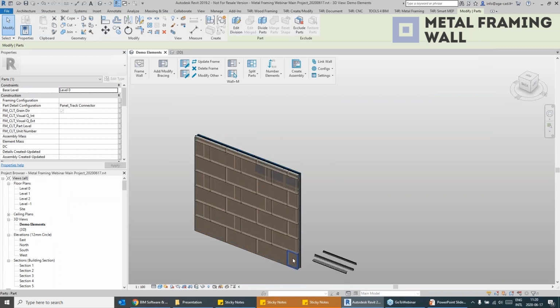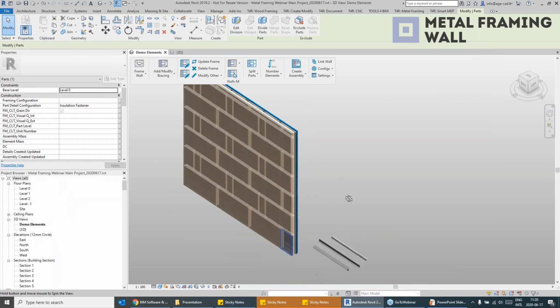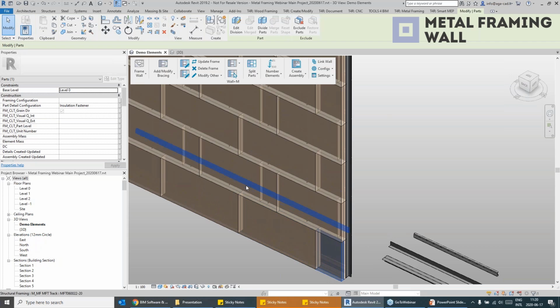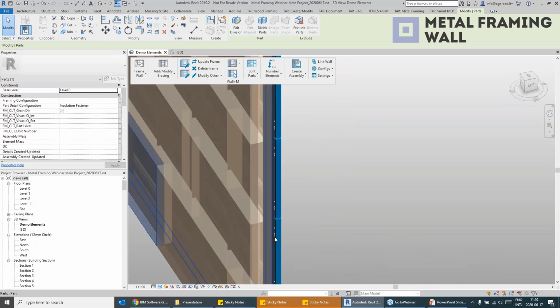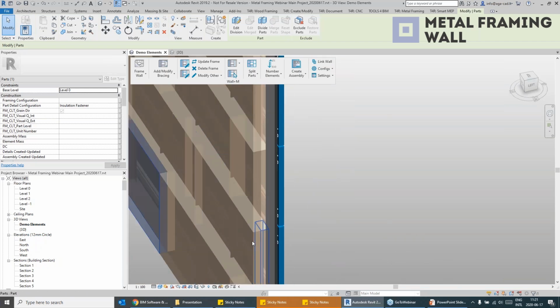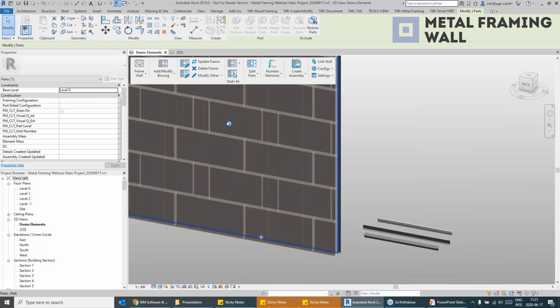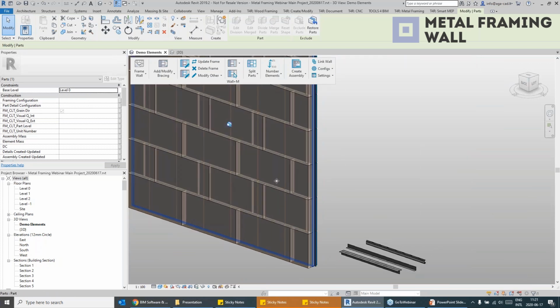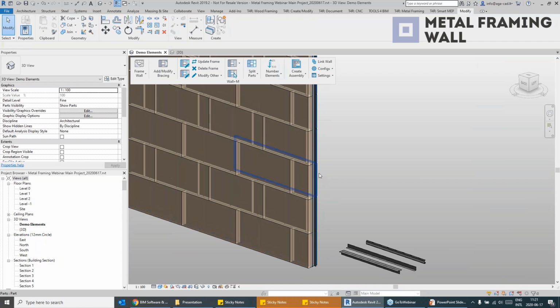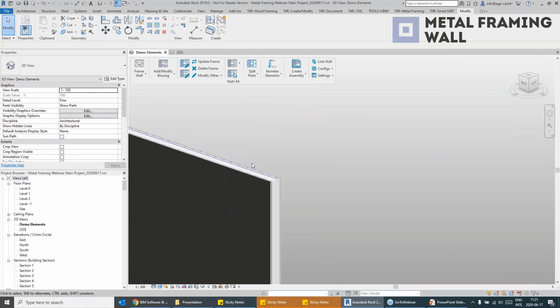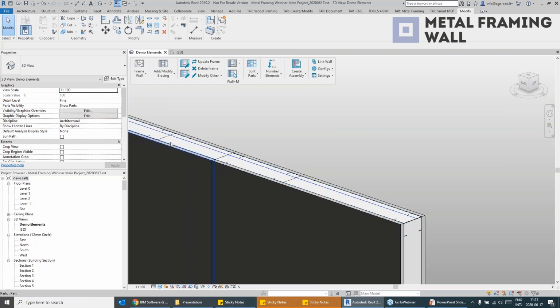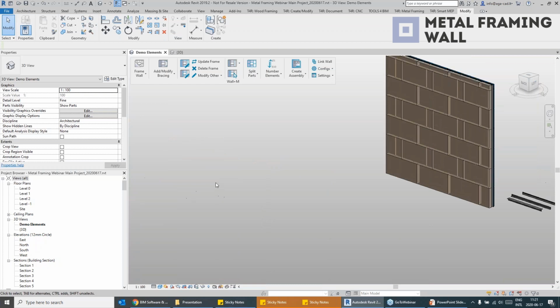And also, as you can see on the interior of my wall, I've got staggered splits. And actually I've got two layers to be split because I have an insulation right here. As you can see, easily you can split your parts and get insulation. You can get panels, you can get sheathing, as well can you place insulation between your studs and split your parts by studs, and then you have insulation just inside of your frame.